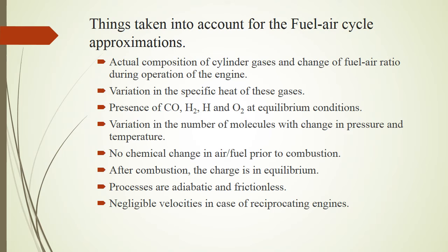Apart from these things, a few other things are also important. There is no chemical change in either fuel or air prior to combustion. Just after the combustion, the charge is always in chemical equilibrium. There is no heat exchange between the gases and the cylinder walls in any process, that is, processes are adiabatic. Also the compression and expansion processes are frictionless. In the case of a reciprocating engine, the velocities are negligibly small.